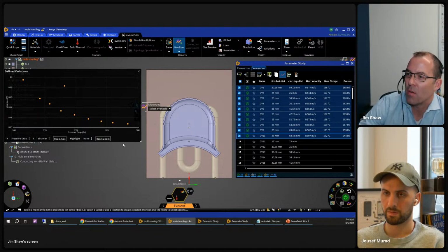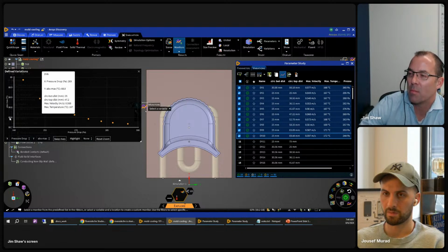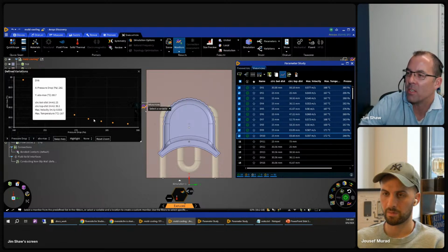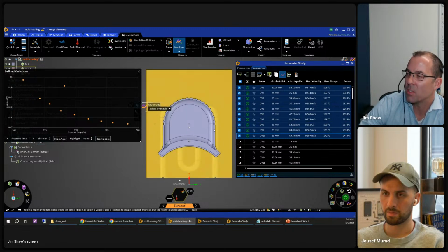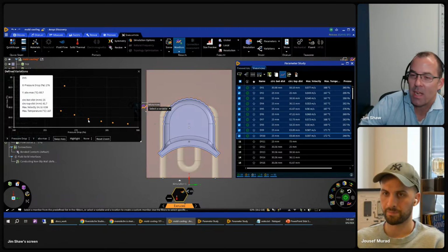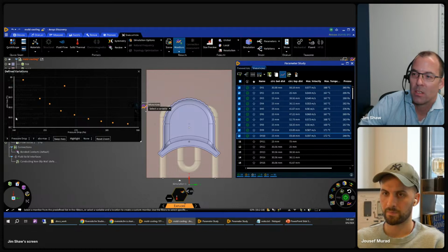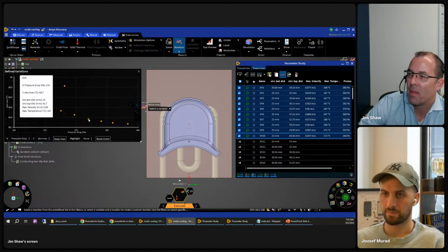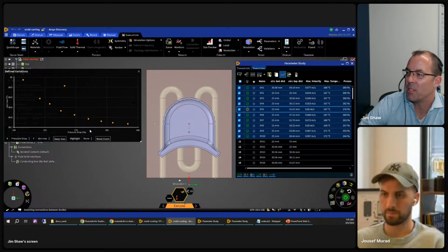And so what we're going to be looking for, for example, is let's say I had some maximum temperature that I wanted to maintain. Well, let's say I wanted to be below, I don't know, in this case, 88.8. This is pretty precise here, but let's say I want to be below some certain temperature. I'll have 3 or 4 or 5 or 6 different designs of our conformal cooling circuit that meet that criteria. So what's the second criteria? Minimize pressure drop. Then I'm going to go to this guy right here. There it is, set to current. And this is going to update the geometry. Boom.